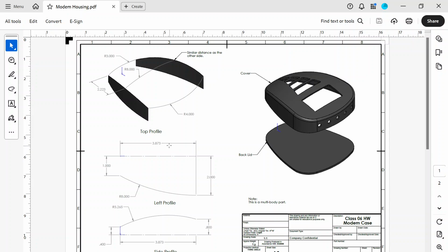Then going back, you will see that three sketches should be drawn, and from the previous exercise, we know that we have to create three separate 3D sketches for each portion. I'll start from the back, and then with all these three surfaces and the edges of them, you are going to use a lofted surface or boundary surface to fill the top portion. So starting from this back curve here, it sounds like there is a radius of 3 inches, which would be the one that we have to select here.